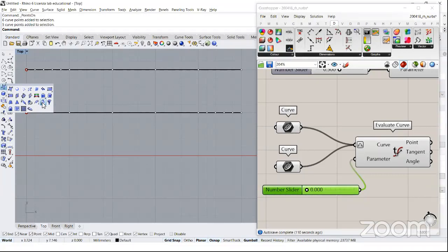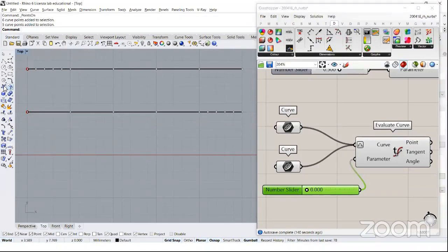Because the speed along the rail is important in order to control how fast the two extremes of an eventual cross-section move or slide along the 2 rails. So this particular configuration might produce some twisting of the surface or some torsion along the sweep. So it's important to control the topology of the curves, even when you are working with surface creation, especially when you are working with surface creation.